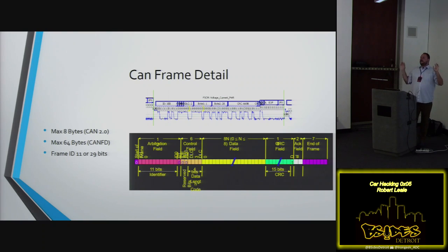And what happens, and this is where it's really, really crazy at a very fundamental level with CAN bus, is the transmitter will throw away the message that it transmitted. All of the receivers will throw their received message away. They'll notify the application, hey, I got an error. They won't tell it what happened. All of this data is just thrown into the garbage bin. The application that was monitoring it will have only limited information as to what was there and why it happened. They'll say, oh, somebody didn't get it, so don't worry, the transmitter is going to resend it. Okay, well, guess what? The transmitter can only do that so many times before it will stop. There's a little fault containment.